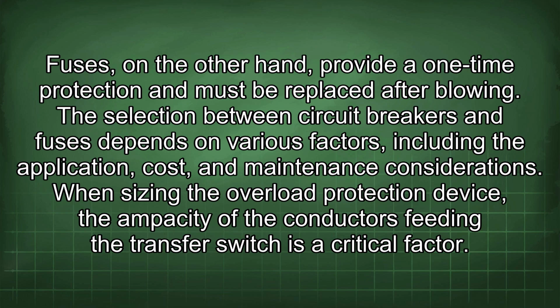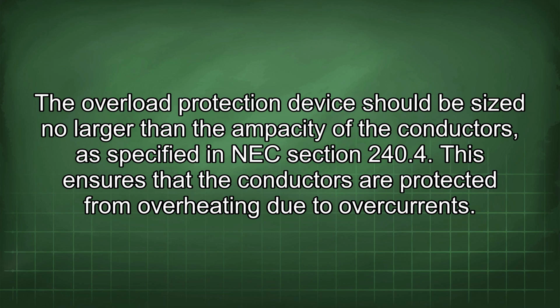When sizing the overload protection device, the ampacity of the conductors feeding the transfer switch is a critical factor. The overload protection device should be sized no larger than the ampacity of the conductors, as specified in NEC Section 240.4. This ensures that the conductors are protected from overheating due to overcurrents.